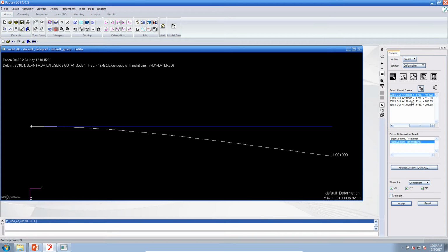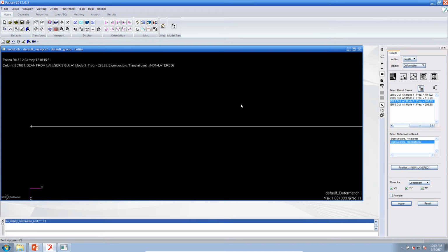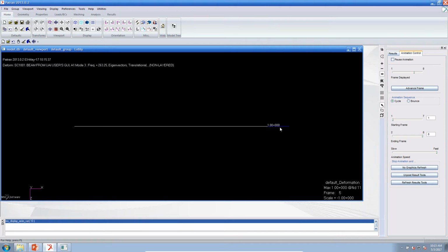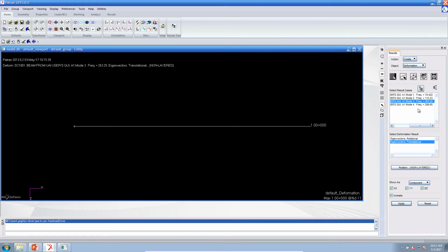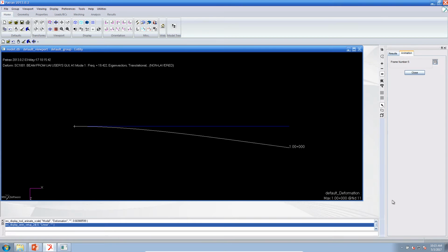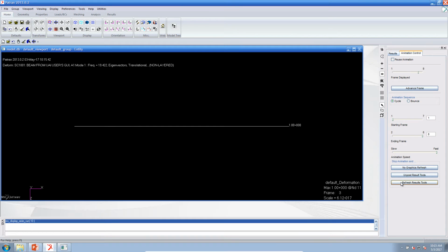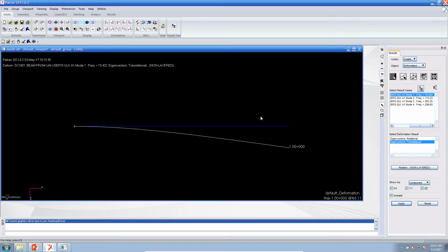You can see it's a bending mode shape. And then mode shape 3, that is an extensional mode shape. So it's going in and out. Maybe I can actually animate that if this lets me. So here's the third mode shape. And then the first mode shape is here. Again, what we want to do is modify a parameter so the mode shape better matches our experimental mode shapes.